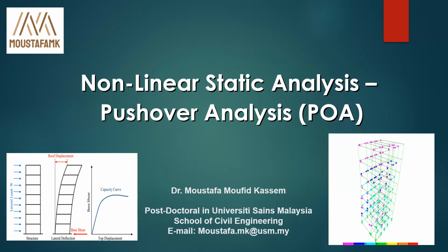In this session, you are going to learn how to develop a model using SAP2000 and also ETABS, for developing a capacity curve based on the pushover analysis. Let me first highlight the meaning of non-linear static analysis. Nonlinear static analysis is commonly referred to as pushover analysis, which is a method that helps determine the ultimate load and the deflection capacity of the structure. You can know the ultimate load and the deflection capability of a structure.